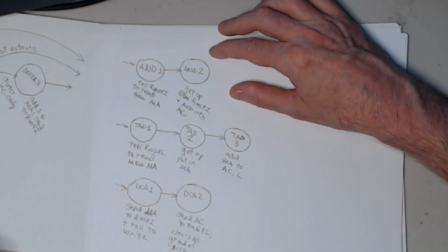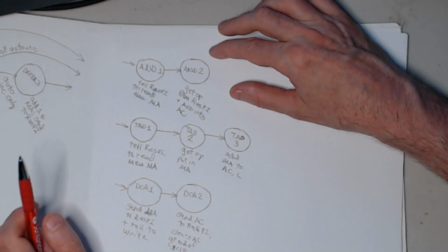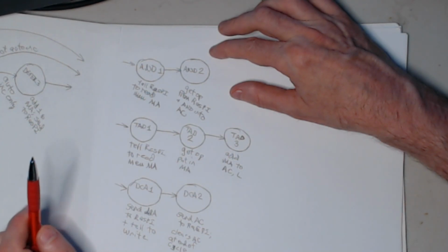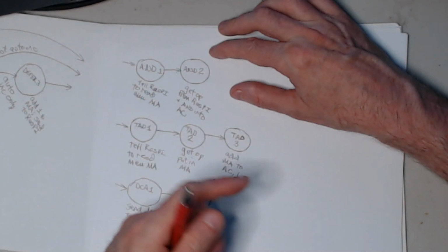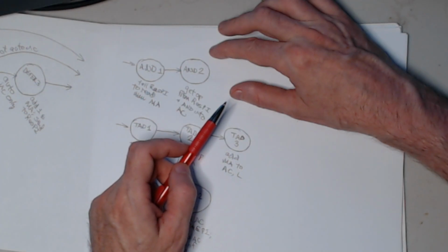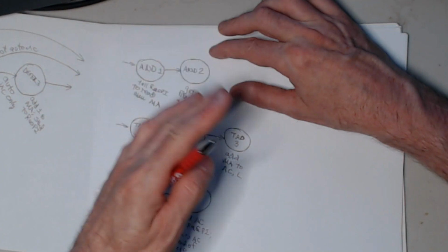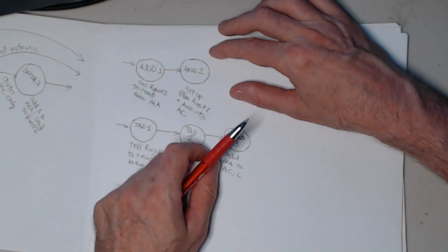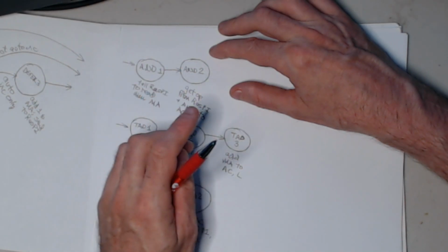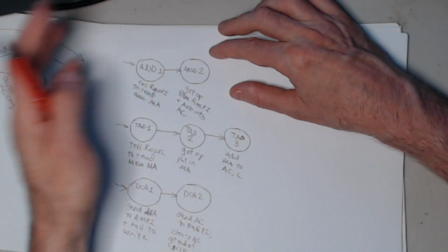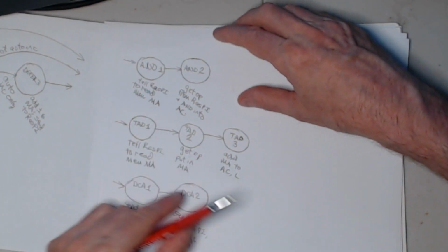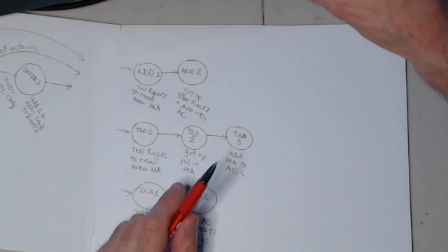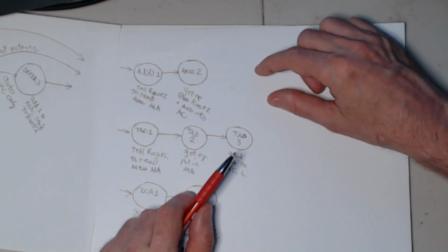And what do you got? JMS and jump and all those guys. Jump just takes the memory address register and writes it to the program counter. So it's not really interacting with the Raspberry Pi at all. It's already got the address in the memory address register, it just writes it to the program counter. That's how jump works. JMS writes the old program counter.